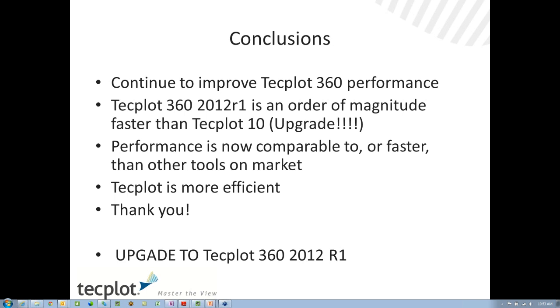It does not recompute the stream traces. To keep the stream traces from going through the geometry, sometimes it offsets a little bit. It's a very simple offset, and it's using the computed stream trace. So the answer is no, it doesn't recompute the stream traces.